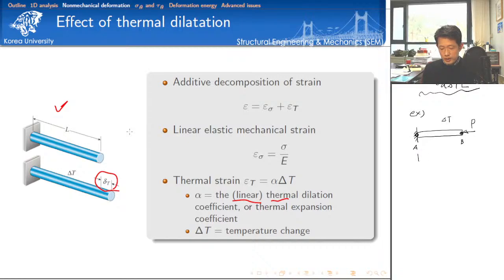Before we start any analysis, we need to put a coordinate system here. Then I can plot the displacement field. Because there is no load in the member, and the prismatic member has a uniform elastic modulus, the strain distribution is homogeneous, isn't it?